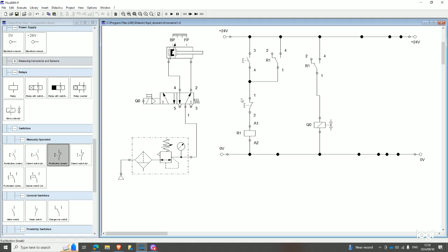This push button, if you look at it, is normally closed. So as soon as I press the first push button, current will flow through it to the relay, sending a signal to the changeover and making the cylinder advance. It will allow current to flow through it up until a point where I need to cut the current. Now I can just press it and it opens up to cut the current and then closes back down. Okay, so let me fix this, and we are ready.